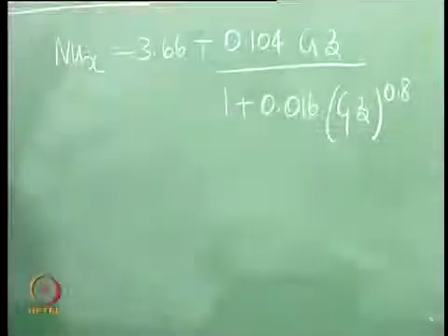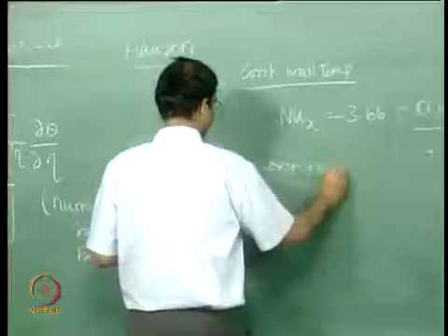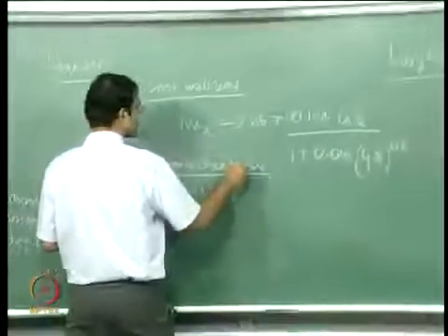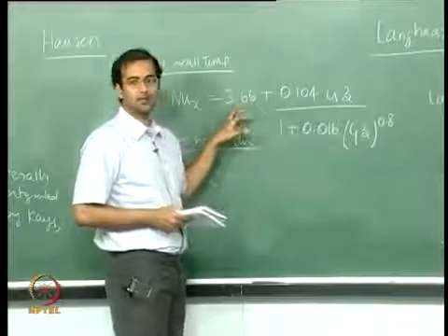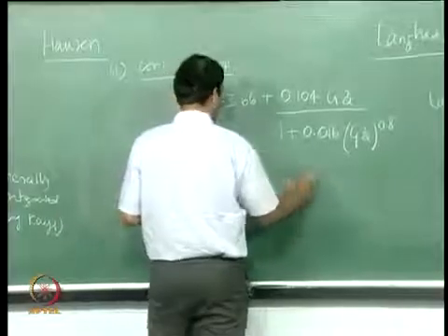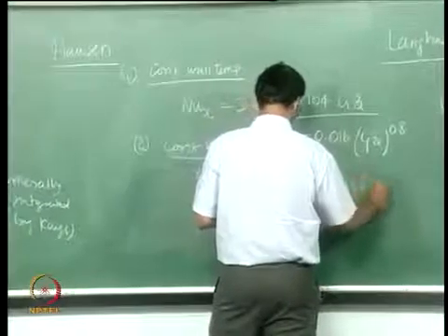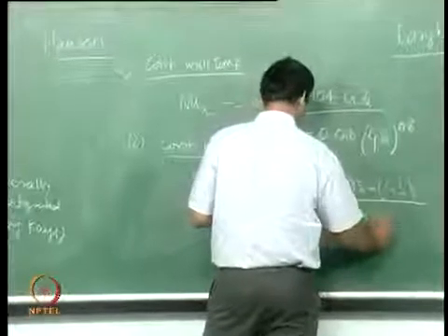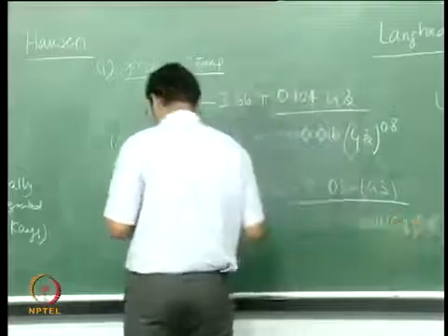And the constant heat flux case. So you see the limiting case where your Graetz number goes to 0 for large values of zeta, so it goes to the fully developed. Okay, so 4.36 plus 0.036 into Graetz number divided by 1 plus 0.0011 Graetz number to the power 0.8.